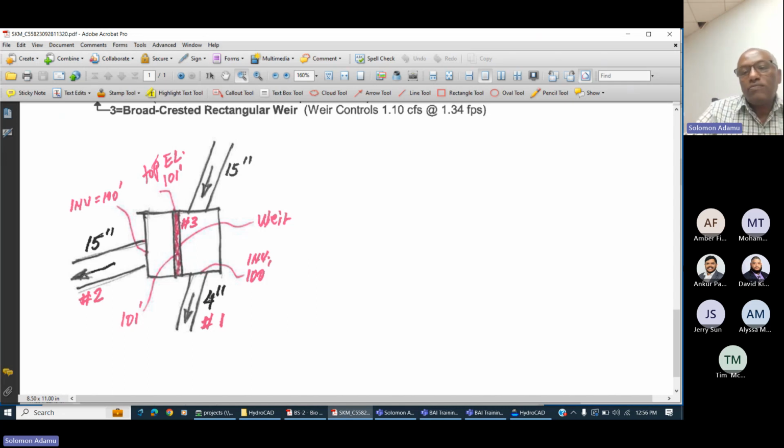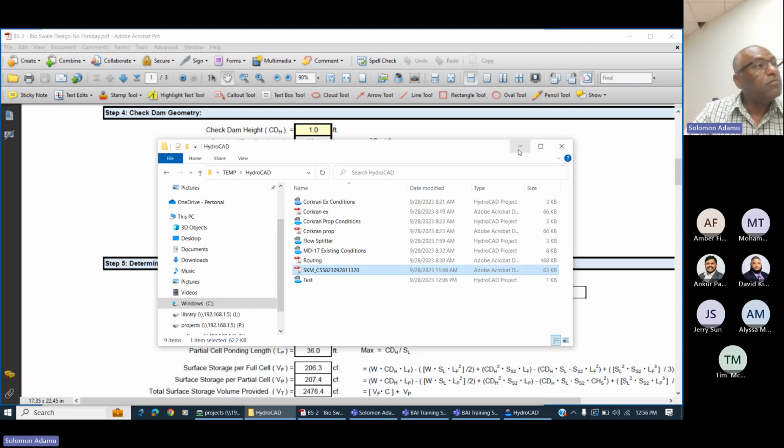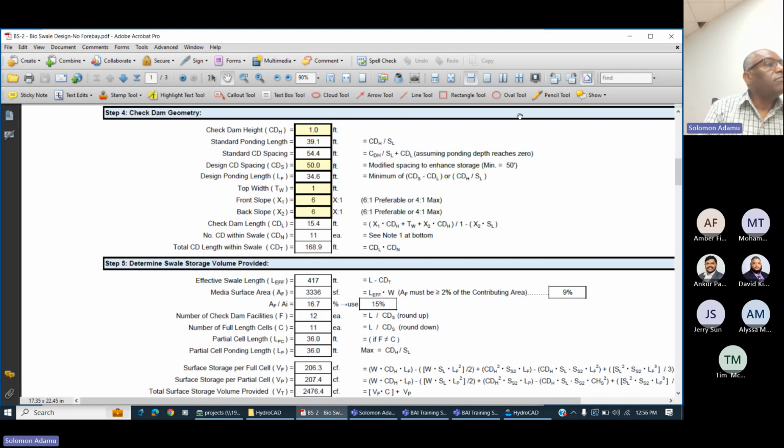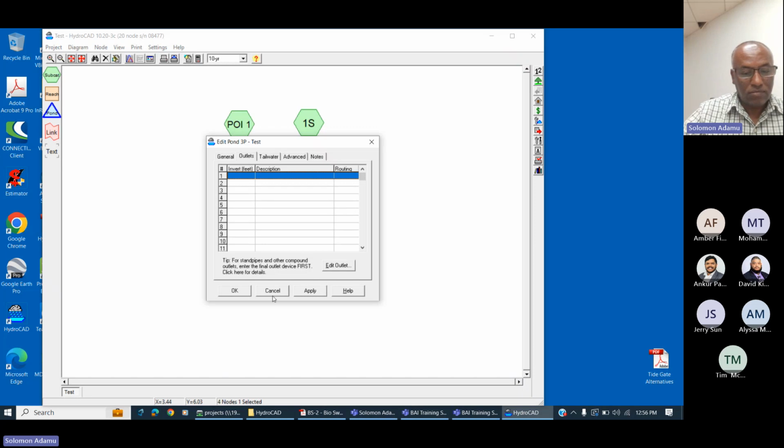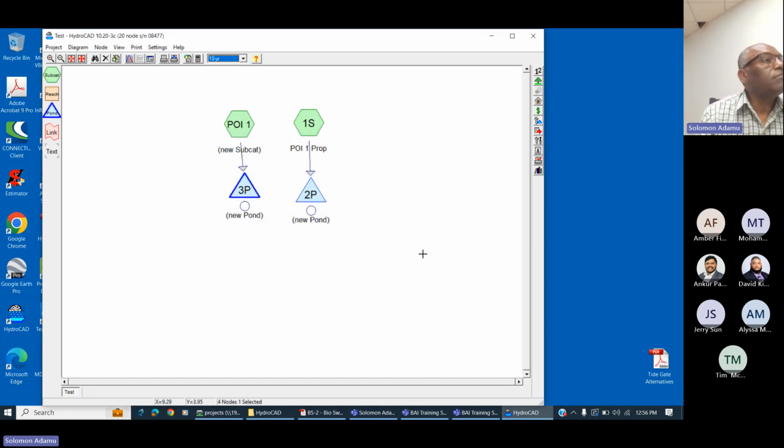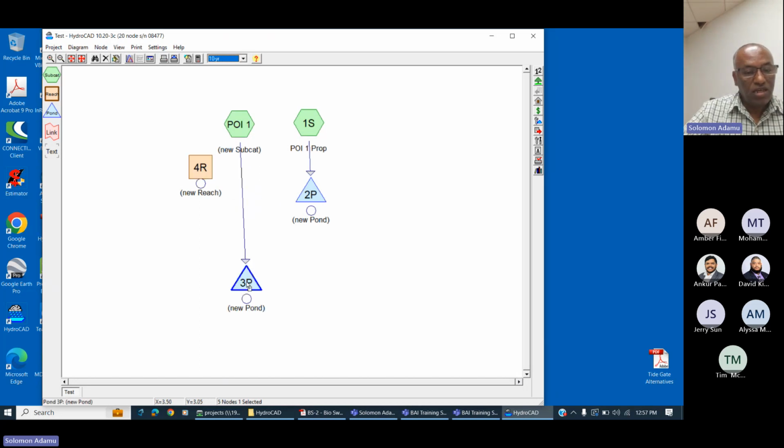Okay, good. So go ahead, ask questions. If you have any question, please ask. So, let's say we have an outfall that has two sub drainage areas. There's sub drainage area A, and that goes through a channel, and then there's sub drainage area B, which outfalls directly to the outfall. How do we show that? Yeah, you're going to need a reach for that, maybe? Yeah, and then draw the arrow from there.